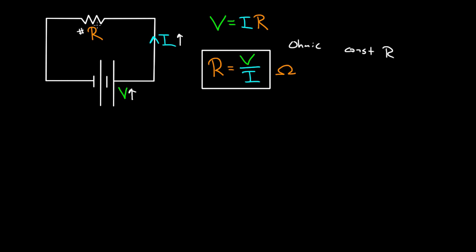I don't suggest you do that. So there's an operating range here, but if you're within that range, this resistance, this number of ohms is a constant. It stays the same no matter what voltage or current you put through it. So we define it by talking about voltage and current, but it doesn't even really depend on that. If you really want to change this ratio, this number that comes out here for the resistance, you need to change something about the resistor itself, its size, what it's made out of, its length, its shape. So let's figure out how to do that.